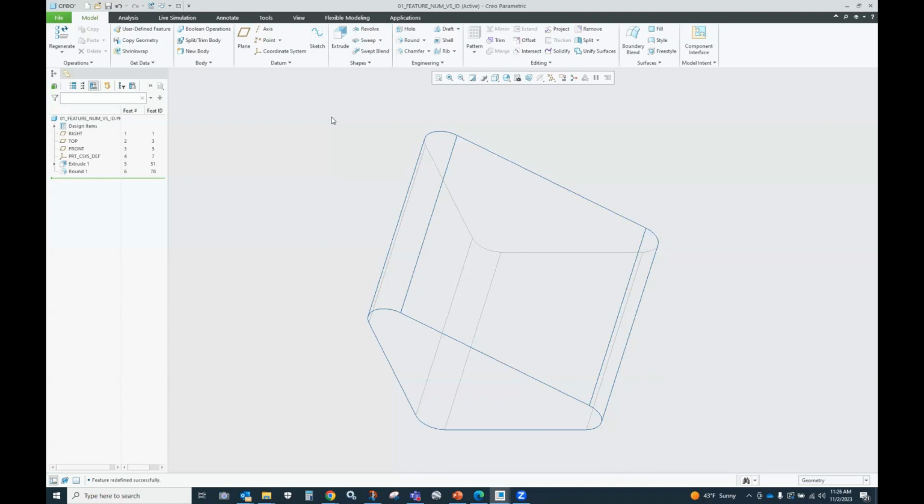That's how Creo works. And that's why, if you look on disk, Creo part files are so small: it's really following a set of instructions on how to build the model. It's not the physical 3D geometry or 3D model. It's building the model based on a list of instructions. So the better you are at writing that list of instructions, the easier it is for Creo to regenerate the model, and in most cases, the model is more robust.